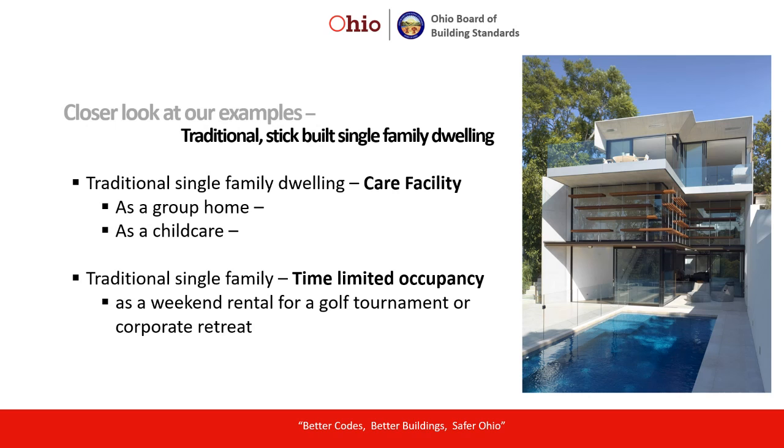There is one exception that allows a care facility with 5 or fewer lodgers or boarders to remain a single-family dwelling regulated under the Residential Code of Ohio, and that's if all the recipients of care are capable of self-preservation.